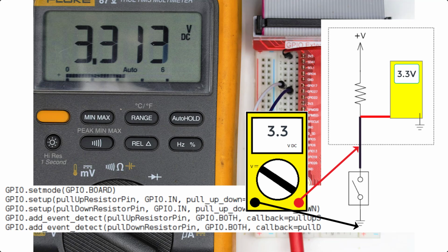In order to ensure that you correctly understand what we're measuring here, that internal voltage sense is not the representation of the meter reading that we're currently getting, or the meter and its position in the circuit. So here I have drawn our meter. This is the meter as represented by the one that we see in the image. Where we're checking for voltage is on the exterior of the Raspberry Pi. That black wire that's coming out of the dashed box is physical pin number 11. So when we're making this measurement, we're actually making it external. It just happens to match the internal voltage sense measurement.